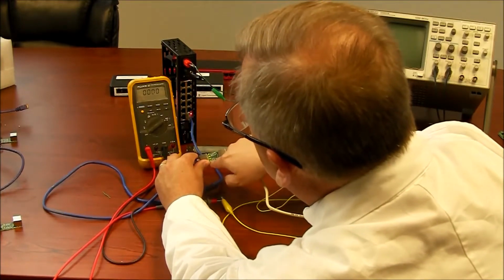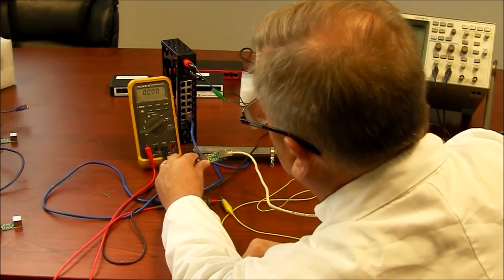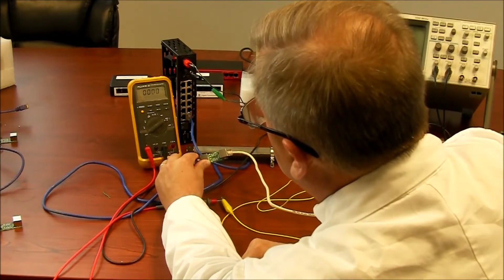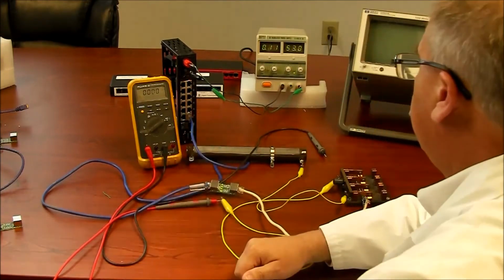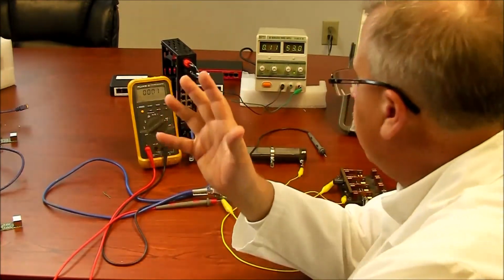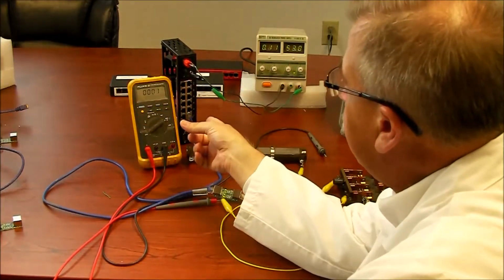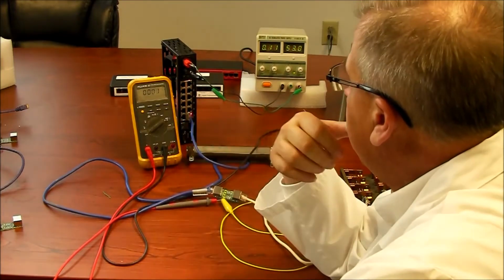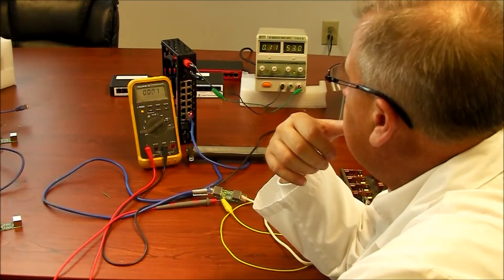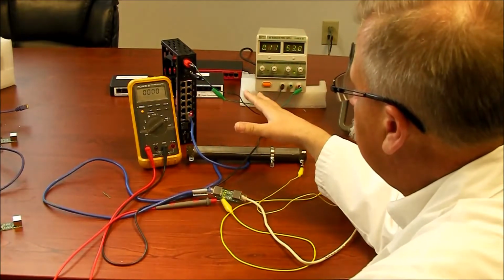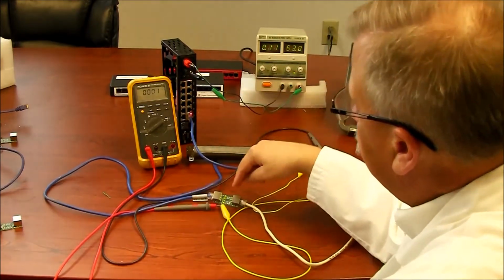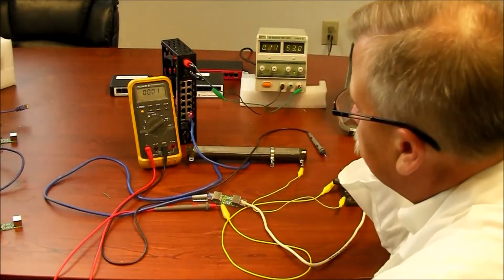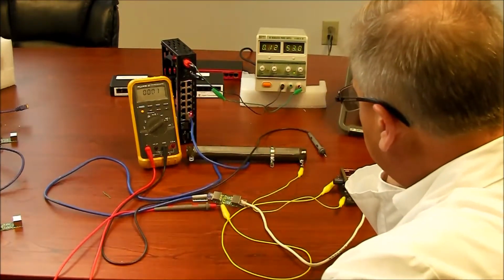Port did not blow. Port's still making all the voltage it's supposed to. And so I think I picked a pretty good spot for the fuse. You're going to get your fully rated 2 amps plus out of that thing. And you can rest assured that if the current goes too high, it's going to blow here before it blows there. I think I can make that assurance, okay?